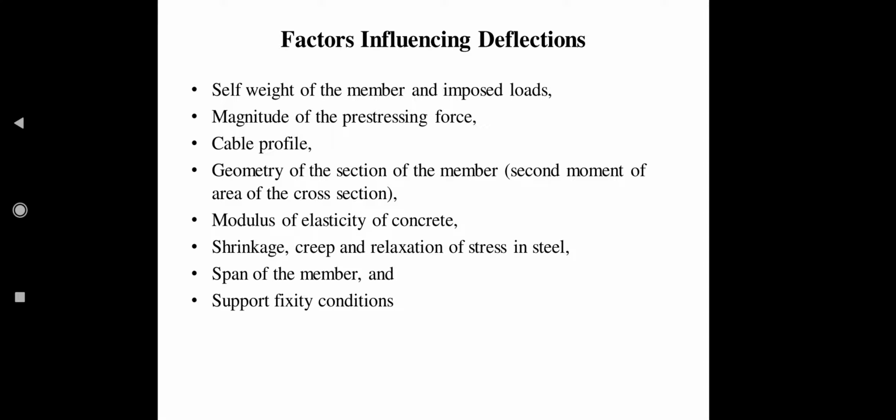Magnitude of pre-stressing force. If the magnitude of pre-stressing force is less, then the deflection is more, because the upward thrust or upward force that is exerted by the cable will be less, and as a result of this there will be deflection.